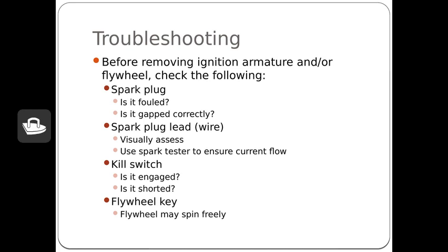It could be misgapped somehow. Maybe you put a new spark plug in, you didn't realize that you set it down too hard, or maybe you dropped it and it closed the gap, or perhaps it was just made wrong and it's not gapped correctly, it's too wide. Older spark plugs, we used to have to gap them all. They pretty much come pre-gapped now, but it's never a bad idea to use our feeler gauge or our spark plug gauge to check that gap.